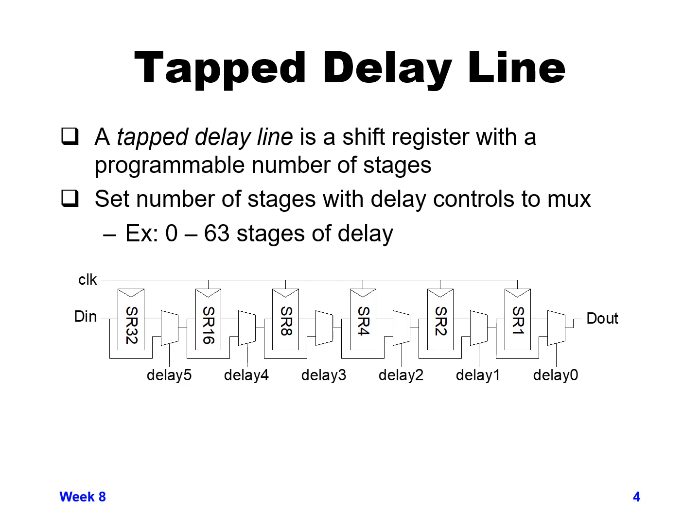So if we allow delay 5, 4, 3, 2, and 1 to all choose the value of D in that goes around the shift register as the value that goes through the mux, then when D in comes in, it goes through the mux delay 5, through the mux delay 4, delay 3, delay 2, delay 1, and then let's say the delay 0 mux chooses the output of the shift register to go through that mux.